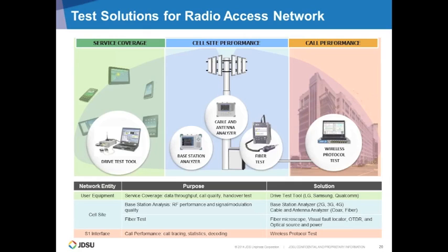But I'm also a big fan of the drive test receiver. Drive test receivers are special purpose, meaning that they have bandpass filters and preselectors, which give a much more realistic representation of how the handset or the base station would see the spectrum. And this is very important when measuring, but the other key advantage is that a drive test receiver is very, very useful in doing multiple bands and multiple technologies at the same time. So they're great at multitasking.